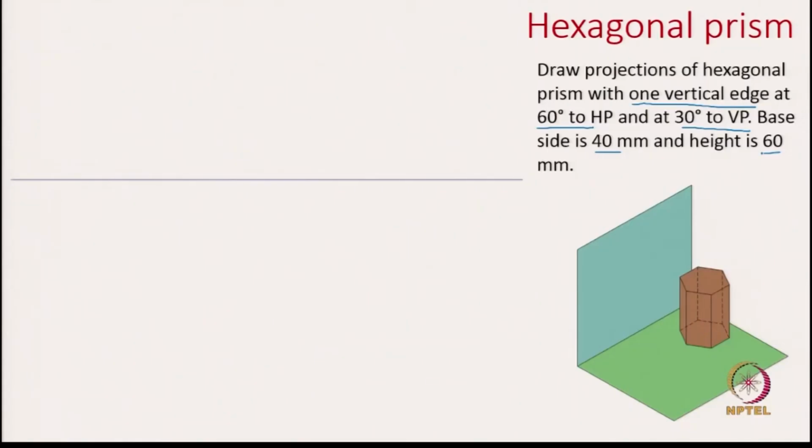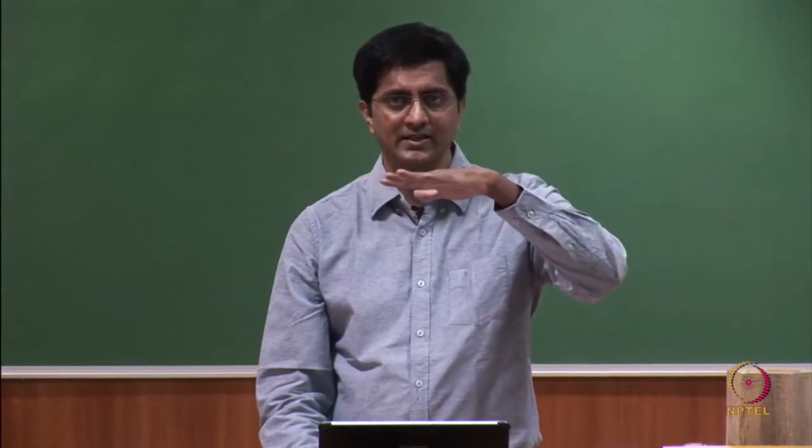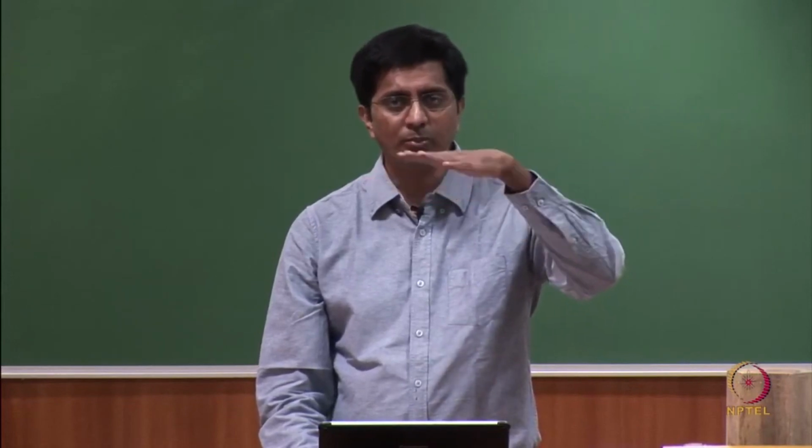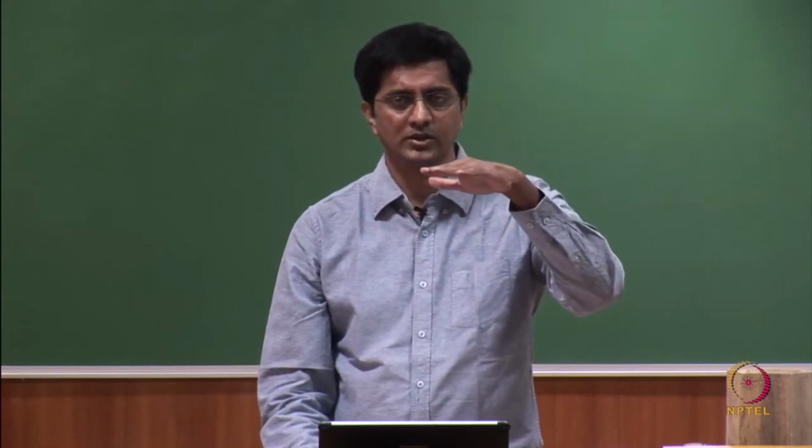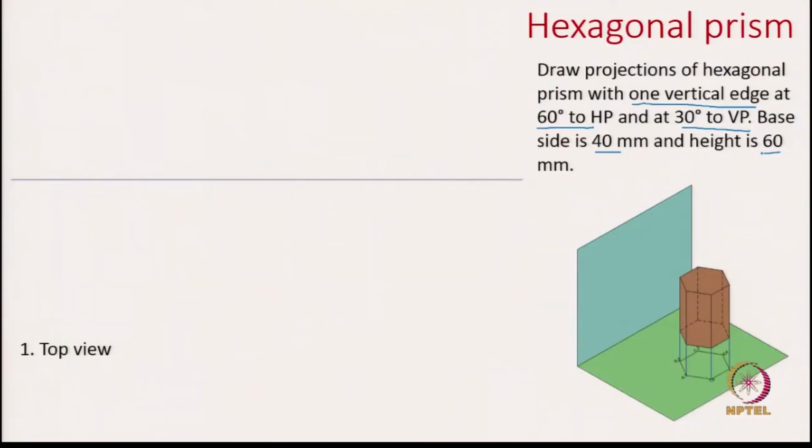So, the first step is of course the simple orientation, and here do we want to start with the front view or the top view? The answer is we want to start with the top view. The reason being, in the top view what you see is a hexagon, because the top base and the bottom base both of them are parallel to the horizontal plane. Okay, so first we capture the top view and this is the top view.